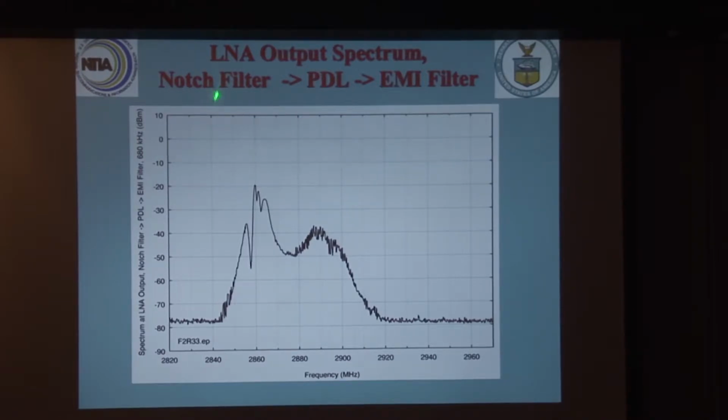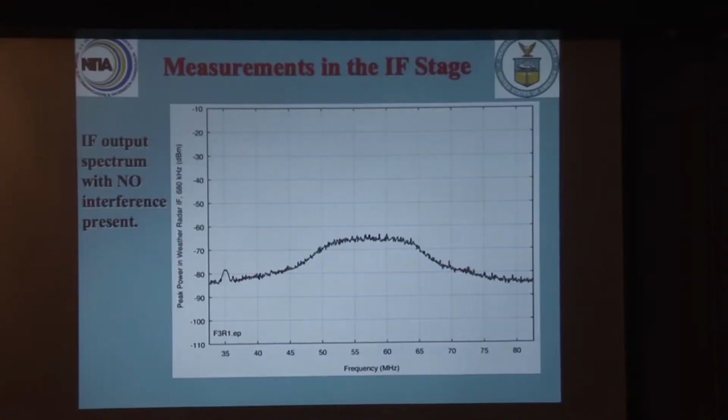We put a notch filter on the air traffic control radar at the frequency where its energy was getting into the weather radar. So here we're notching the air traffic control radar. So now we had to go back over to the air traffic control radar site, put a notch filter on it that notches its unwanted emissions right at the weather radar frequency. And sure enough, the notch works. In fact, you could tune the notch back and forth and watch that go up and down while you're talking to somebody on a cell phone or a handy-talkie between the two radars.